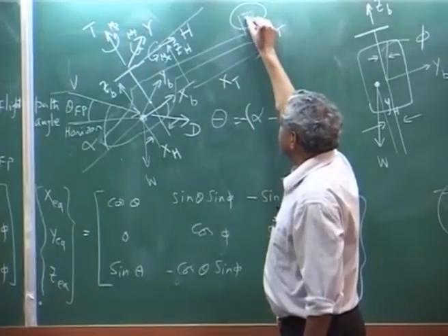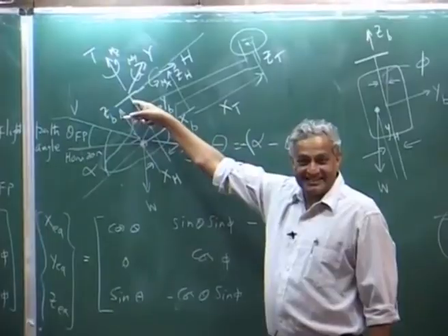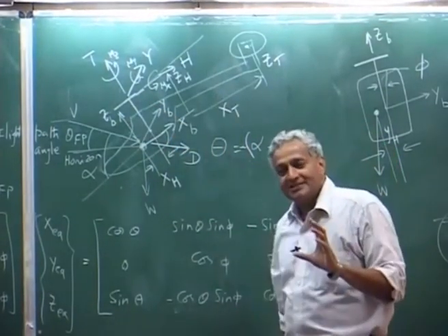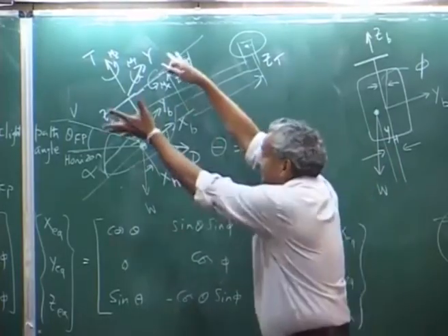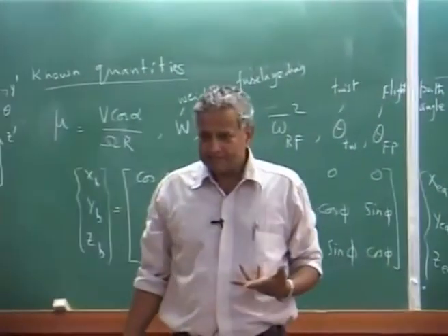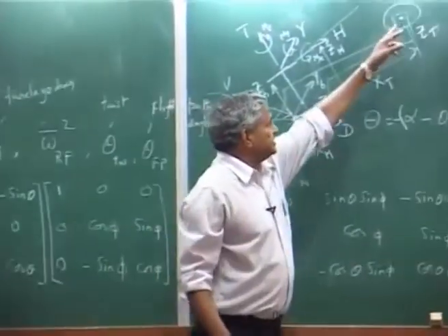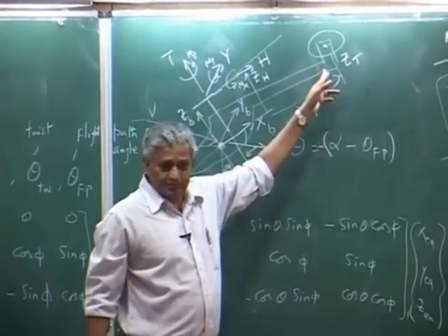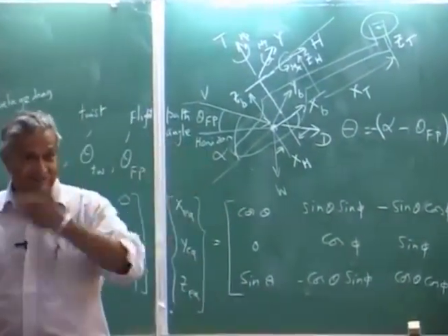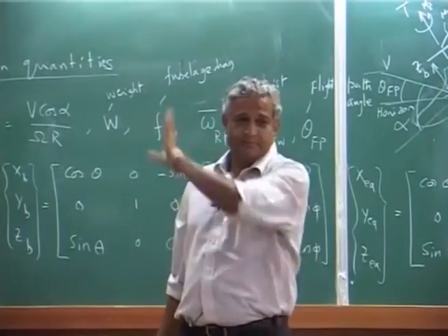So, you try to keep the center along the rotor hub height, so the tail rotor is not affected by the flow from the main rotor. If it gets affected, you do not know what is going on. You do not know how the wake from the main rotor and the tail rotor rotation will interact. So, the best is you put it up.